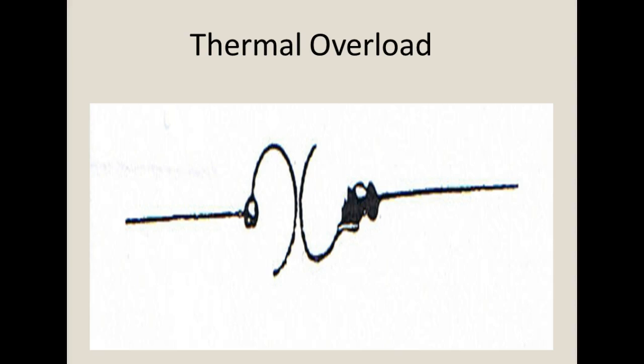If you see this in a circuit and it's pulled apart, that means it's overloaded. This is not something we reset manually. We don't take the top of the compressor off and reset it. It should reset. If it doesn't, it's a dead duck, okay? Everybody got the symbol? Okay. Y'all got it. First test, y'all got to memorize these symbols. So we've got the temperature switch, thermal overload.